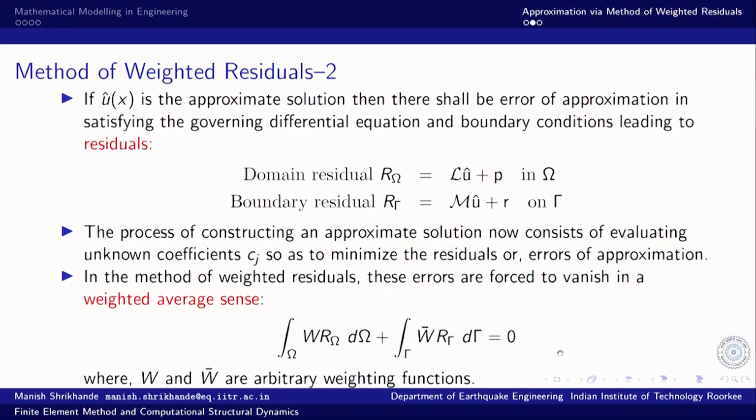So, the statement of weighted residuals would be identically satisfied for any arbitrary functions W and W bar. That is a reassuring thought: in this weighted residual statement, the exact solution is contained.